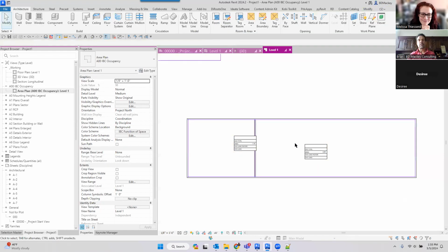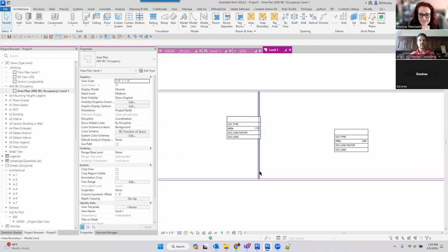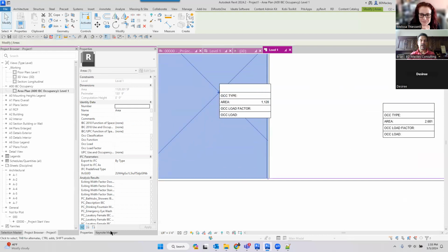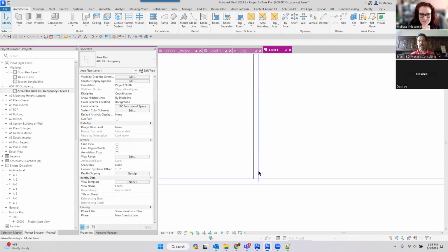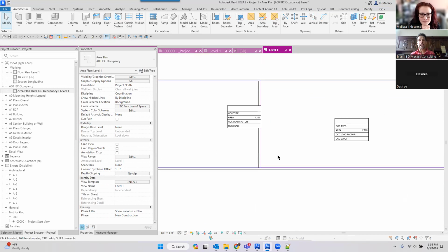Sorry. So then when I come back in here, you can see that this line is centered on that area right now, right? But if I were to say, okay, cool, this is going to be a major vertical penetration, everybody pays for the major vertical penetration. You'll see that it'll automatically move that over to that major vertical penetration. So it can set up those rules for you.